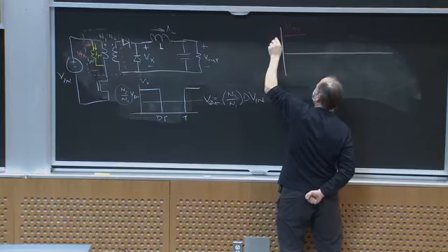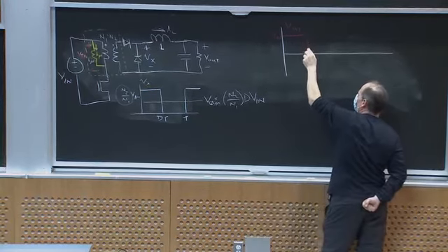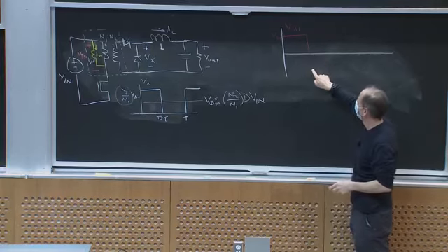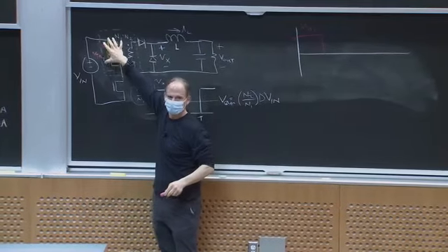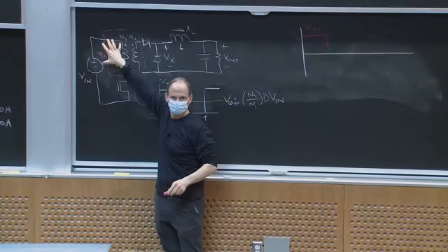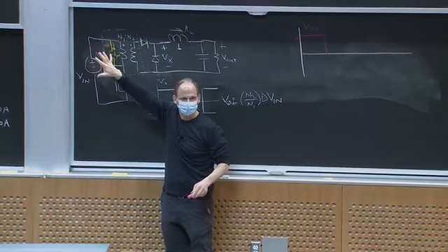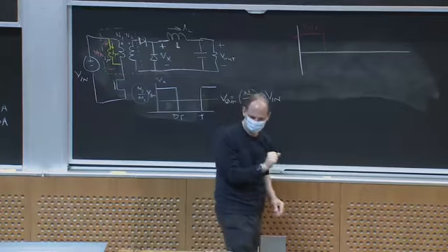And I'm applying Vn. Okay? So what has to happen? In the second part of the cycle, I better do something so that over the course of the cycle, the average voltage across this magnetizing inductance is 0. Right? Well, I've provided no means for that to happen in this circuit. And probably if I built it this way, unhappy things would happen.